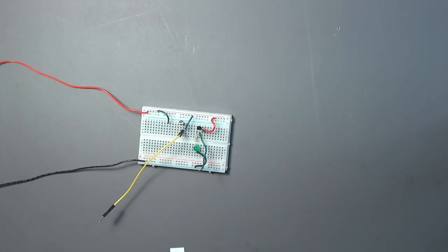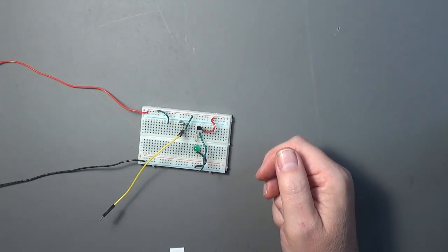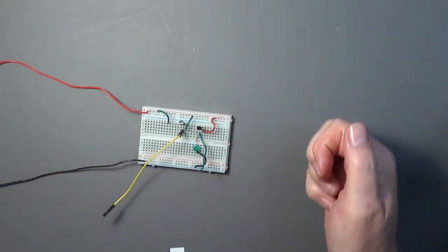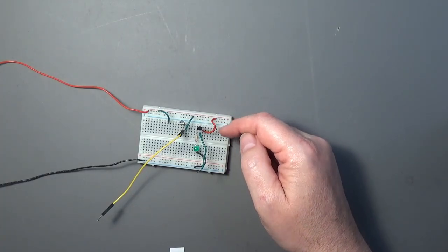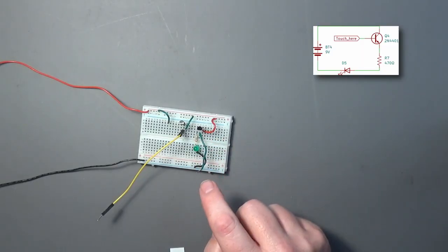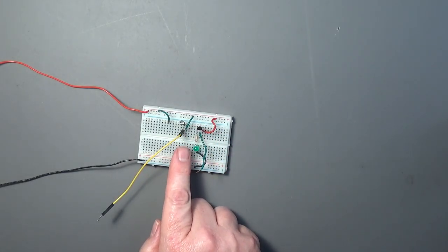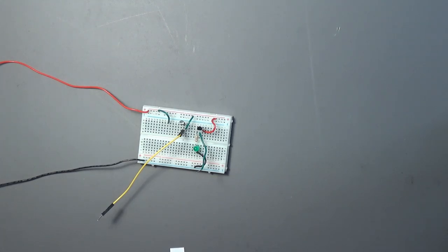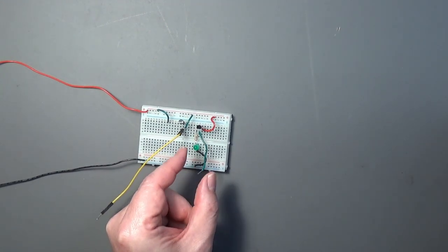A cool thing you can do with amplification and switching with transistors is a little circuit like this. I've got two NPN transistors here. Right now this one's not really hooked up to anything. This one's hooked up to the positive of the power supply, which goes to its collector. Its base just goes to this wire and then through this current limiting resistor through the LED to minus. And if I touch this, nothing happens.